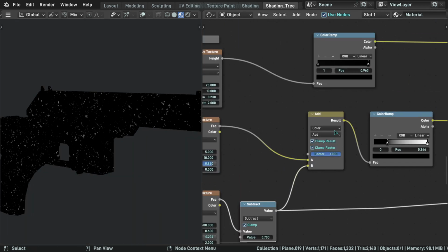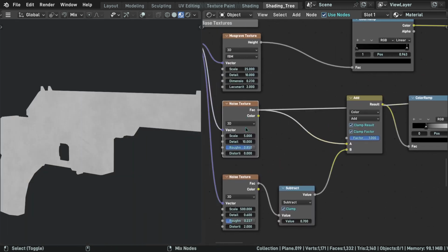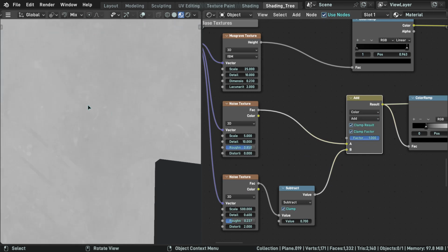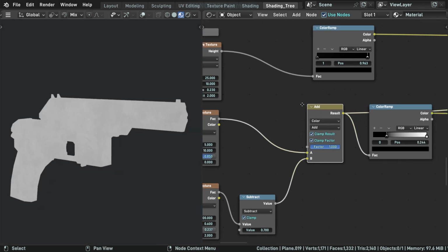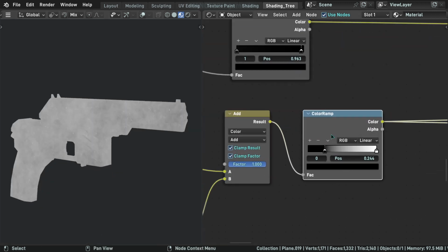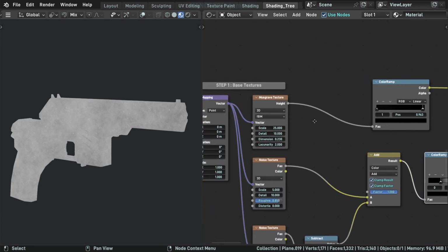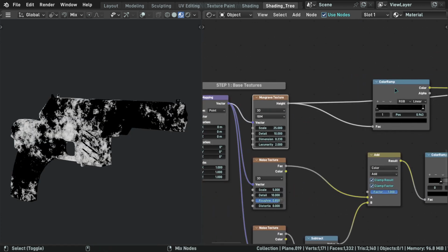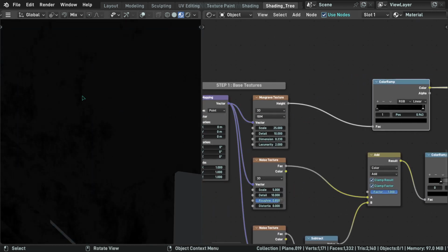So we are adding to a color mix here those particle textures on top. Let me zoom in and mute so you can see it. These tiny speckles will make a difference on the further effect chain. Then after that I just increase the contrast by raising the levels of the dark parts. The Musgrave texture is being darkened a lot and will be used as a base for our albedo color.